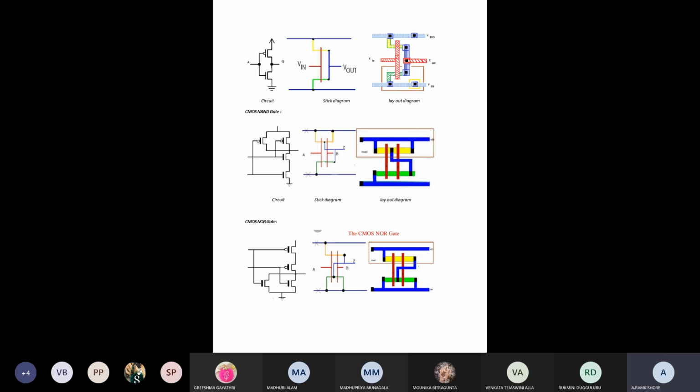For those two transistors, whether P diffusion or N diffusion, the polysilicon works as the gate, so we overlay it across both and it serves as the common input. That is why we overlay the polysilicon color, and it is extended to the input.